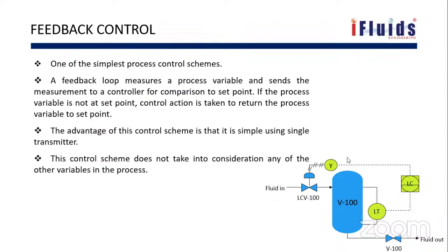Okay. So this is how it is also mentioned in the P&IDs. And now recalling the P&ID legend. These dotted lines are mostly for electronic signals. And this line where you have parallel lines, you can see two different lines here. This is the electronic signal coming up to the control valve. From the control valve, you can see here, it is a parallel line. This is nothing but a pneumatic signal.